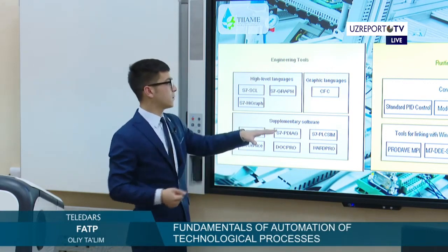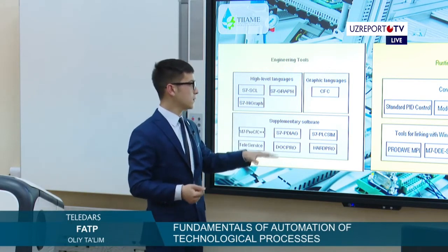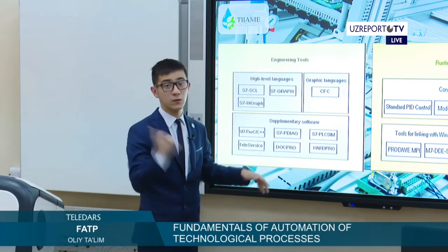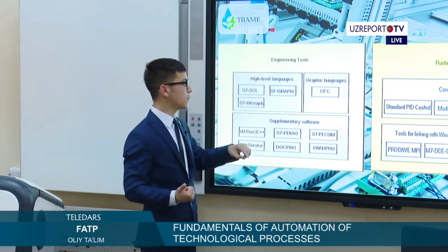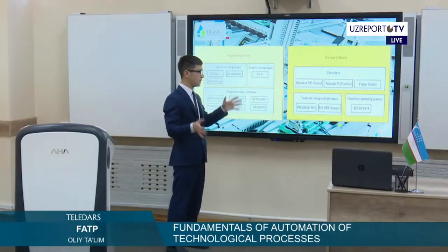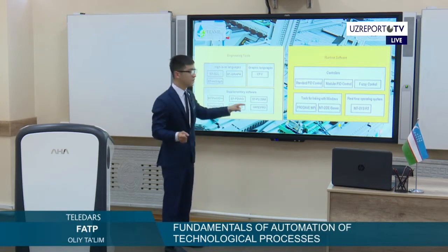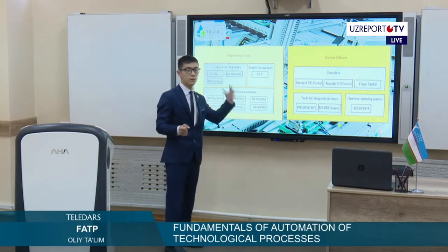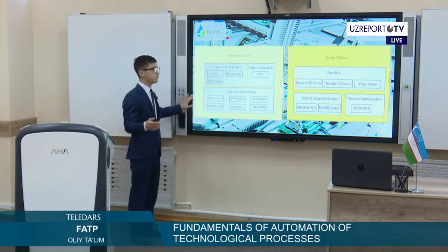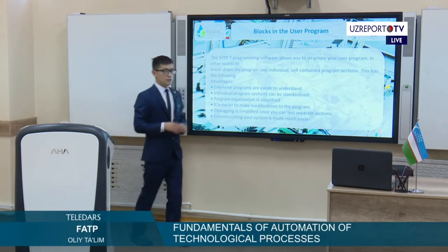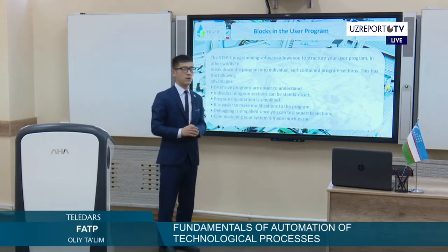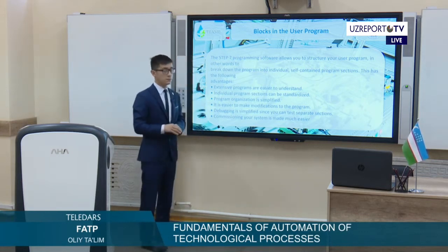Let's talk about the runtime software. In runtime software, controllers, we have PID controllers and fuzzy controllers to make a fuzzy logic. And tools for linking with the Windows, and at the same time, real-time operation systems. They're different a little bit, and today we will use the tools for linking with the Windows, with M7 DDE. Today we will use the block program in language of LD, ladder diagram.